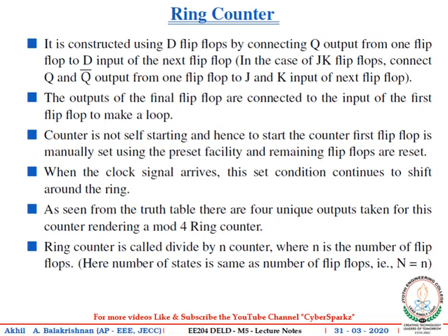One important point to be considered while designing a synchronous counter with a lesser number of valid states is the lockout condition. We have to make sure that the counter is not going into the lockout condition. A lockout condition is such that the counter may eventually fall into an invalid state, and it will not come back from the invalid state to a valid state. So once the counter has gone to an invalid state, it will not return to a valid state. This is just like writing an infinite loop in a C program.